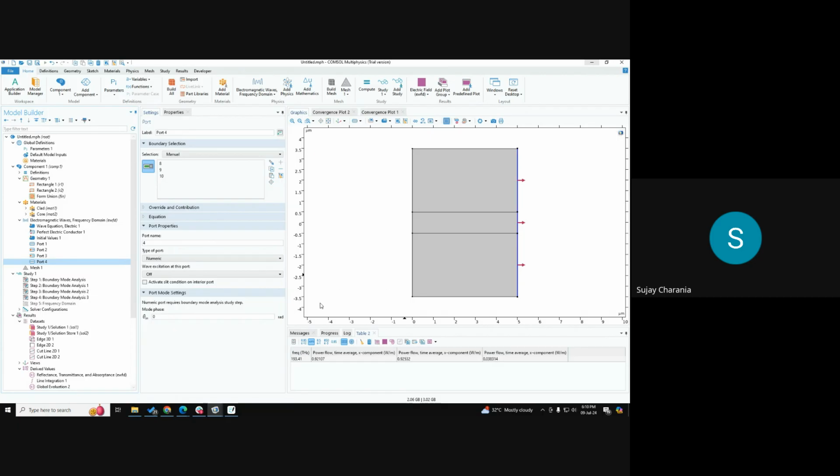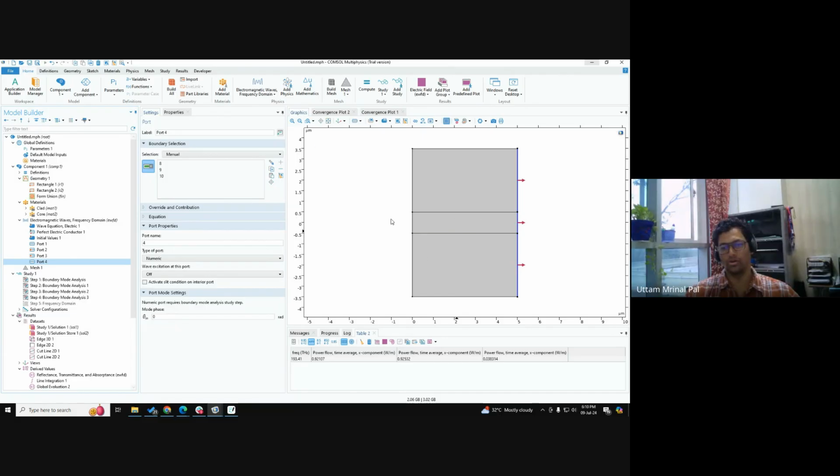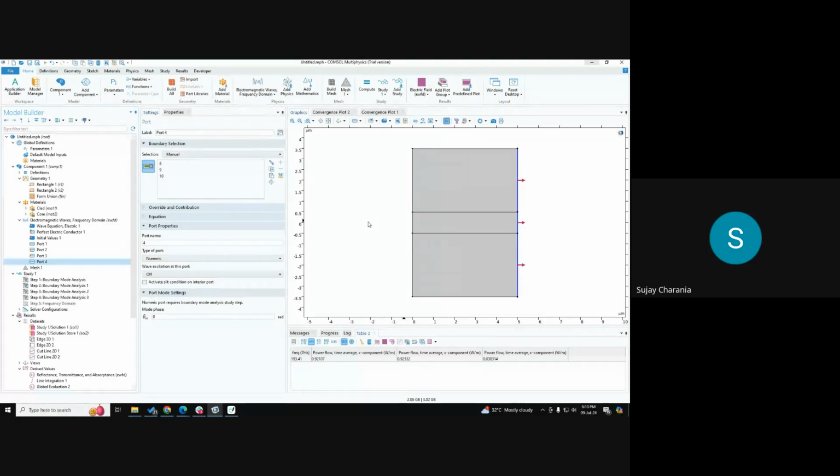But this roughness and bend part, because I have some results from AFM which I could then feed in. This is the roughness you're talking about, the sidewall roughness of the waveguide. Consider you have a slab waveguide, 220 nanometer by 500 nanometer, a typical silicon photonic waveguide, and the sidewall roughness could be given by profilometer or AFM.